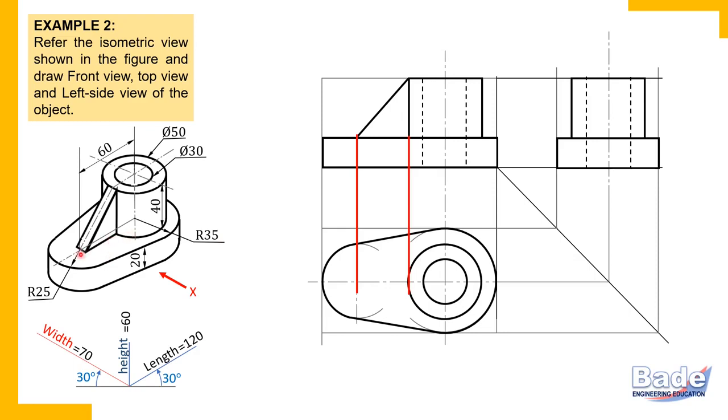This edge is parallel to the length and in contact with the base plate. So this rectangle is the base plate. So, in contact with the base plate at the top, parallel to the length edge, this length. Now, this length you need not measure. It's not given, but you need not measure it either. 60 millimeter is the center of this. That is, from the left end, this corner is 25 millimeters. So from the left end, we have measured 25 millimeters.